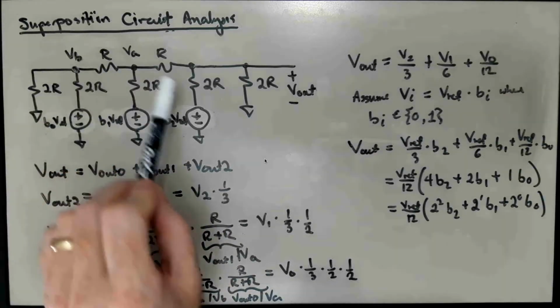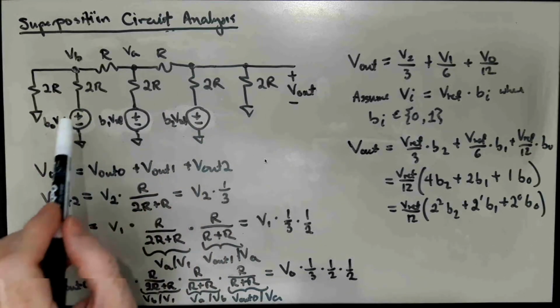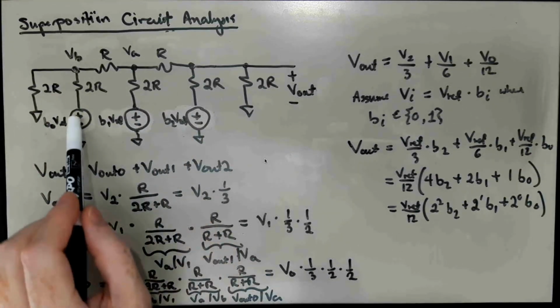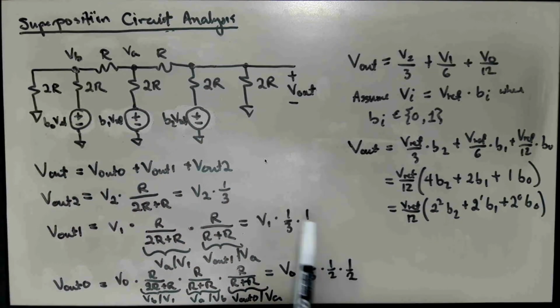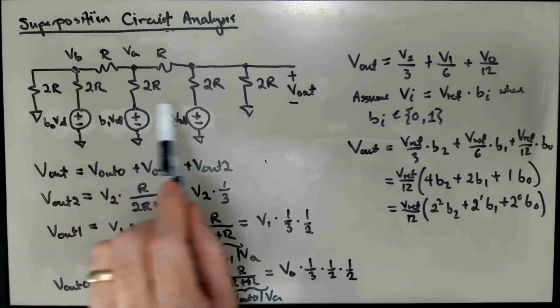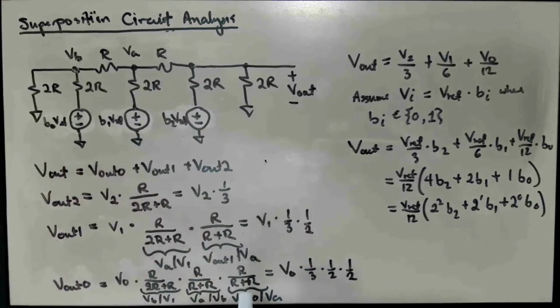And so if you build this kind of resistive network and just put the digital outputs of the microcontroller on these points in the circuit, assuming you've picked your R so that it's capable of being driven by the microcontroller I/O pins, you've got yourself a pretty reasonable digital to analog converter, which is kind of nice because not many microcontrollers come with an actual digital analog converter that produces an output voltage.